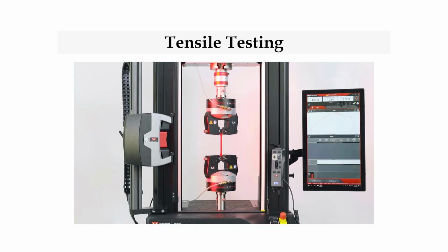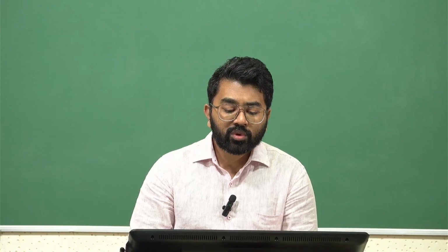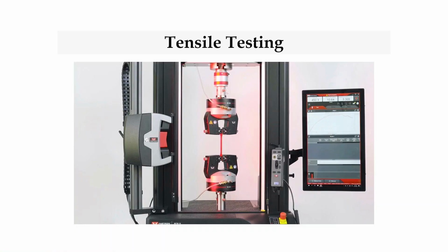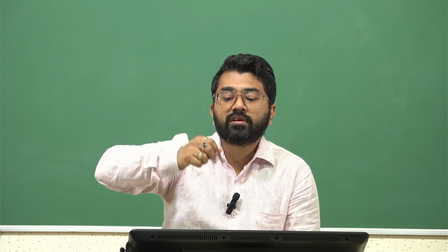So this is what you're looking at from the right side. Okay, further into the tensile testing system, this is a much more professional tensile testing system. This is from Instron. It's a very popular manufacturer which makes some of the high precision universal tensile testing machines. Here you're looking at very sophisticated grips, or clamps, at the top and bottom, which are specifically made for soft tissue clamping, and have very high precision clamping techniques, just to make sure the tissue is not overstressed, understressed, and it doesn't break, right.